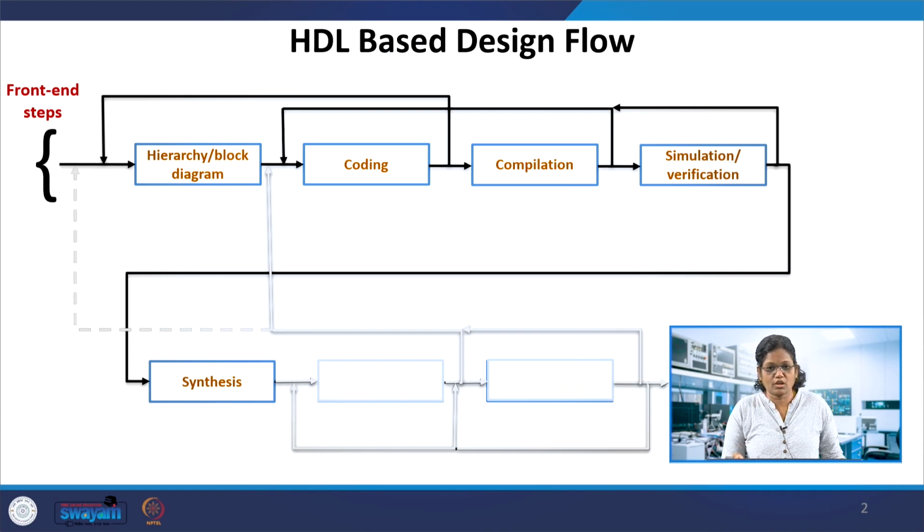Actually, whether the hardware counterpart which you want to deploy in the FPGA exists or not, so your code is synthesizable or not, needs to be considered. Otherwise the whole design needs to be done again, or the Verilog module should be modified. So synthesizable code needs to be written, or the model to be developed.